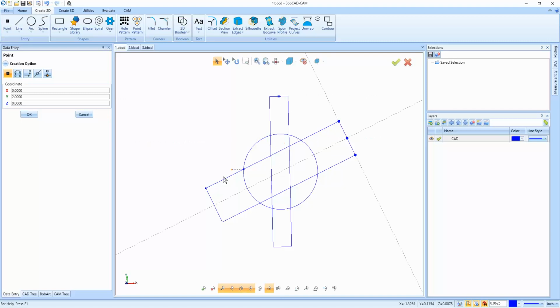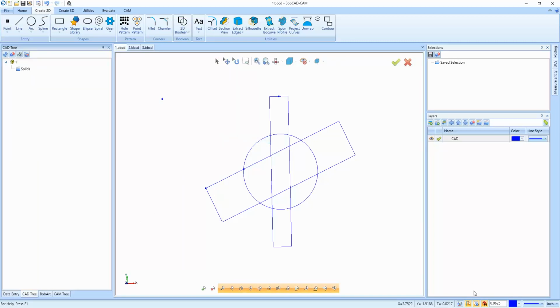You can use these points in this construction geometry in order to line up where things are, right? So sometimes it depends on the order in which you do things, but you can see how you can find reference points and intersections very easily using just the point command and the construction geometry. Now, if you don't see the construction geometry on the screen, there's this option right here down at the bottom, use construction geometry and XY tracking, and you can turn that on or off.